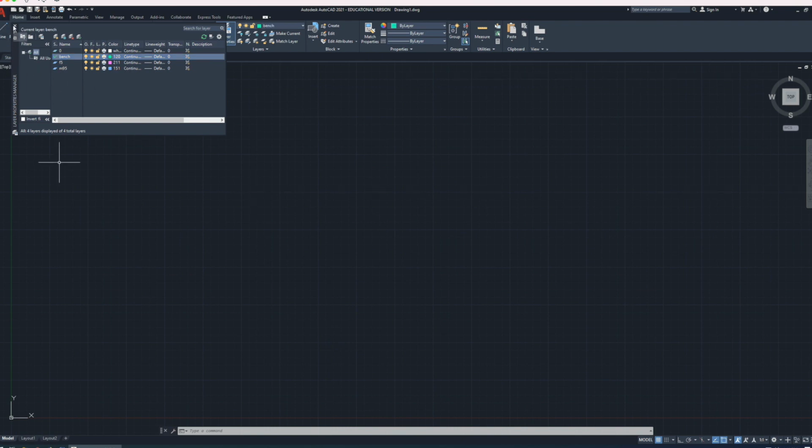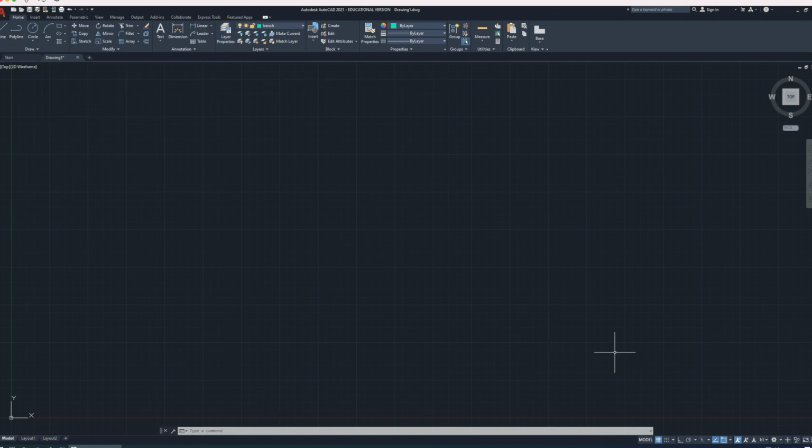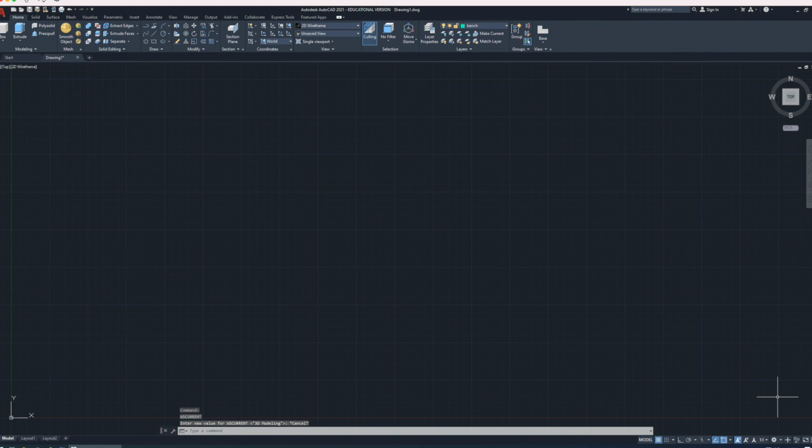So that's active. Now, right now I'm in a drafting view, so I'm going to come down here in the lower right corner. I'm on a Windows machine, so I'll find this little icon that looks like a gear. I'll click on it, and I'll get a pop-up menu, and you'll see it says drafting and annotation. It has a check in front of it. That's where we are now. I'm going to come down to where it says 3D modeling. And when I do that, you'll see I get some extra commands up here, or some extra tool palettes for 3D.